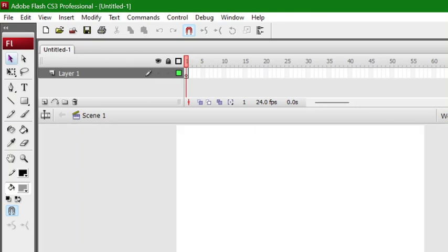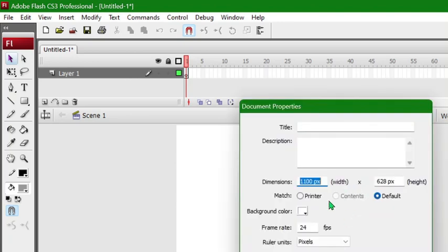Click Size from the Properties Inspector, and then we need to first set the unit of measurement to decimal inches. Next, the size of the paper. We need to create a drawing in landscape format using the legal size.